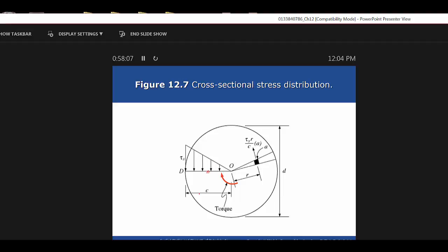Now note down there in table 12.2, there are typical increments that you can buy if you buy the shaft material that you're dealing with. For a half inch up to 2.5 inches, you'll be able to buy it in increments of 1/16 of an inch. When you go to 2 5/8 to 4, you're going to get them in 1/8 of an inch. So if you calculated the diameter at 2.48, that's just a little bit under 2.5, right? But it's more than 2.4375, which would be 2 7/16, right? Well, you wouldn't want to buy the 2 7/16 diameter shaft. You'd want to go to the 2.5.